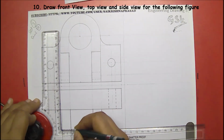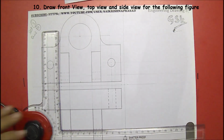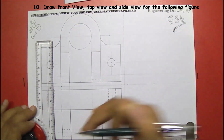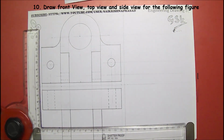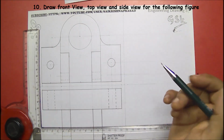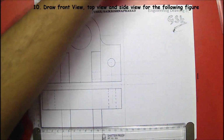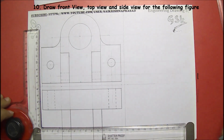For orthographic and isometric projections, it is better to use the drafter fully, with all its features, meaning the angles and the parallel and perpendicular lines from the front view to the top view to the side view, and side view to the front view. Don't use any other instruments for orthographic or isometric projections. For other types of drawings, you can use other instruments, scales and French curve, but for orthographic and isometric, please use the drafter. And please set the drafter for exact tightness for the bench.